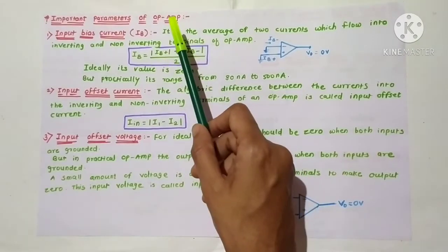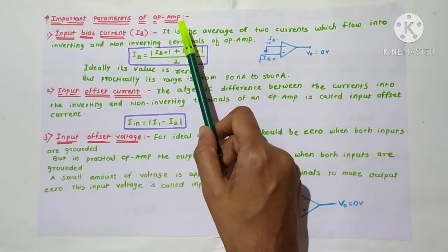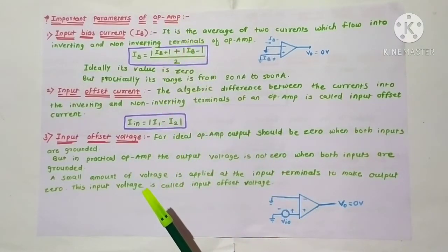Because an operational amplifier produces certain errors which are created by internal imbalance within the op-amp circuit itself. These errors are known as offset. It denotes the existence of DC output voltage even when no signal is applied to any of the input terminals of the op-amp. The other factors are drift and slew rate. All these parameters are to be considered while designing the op-amp circuit.